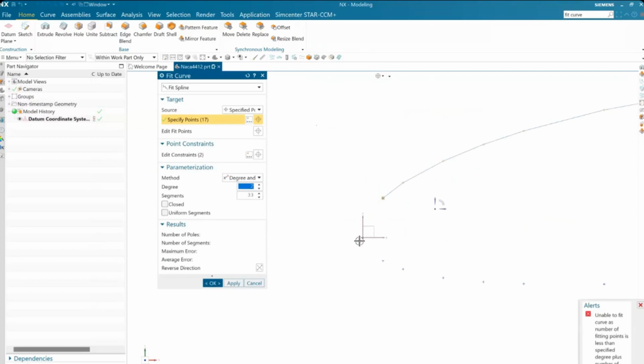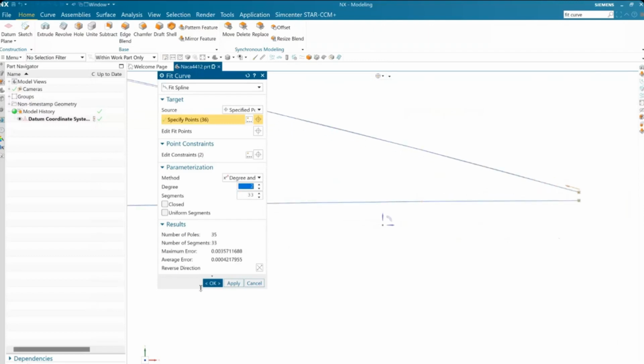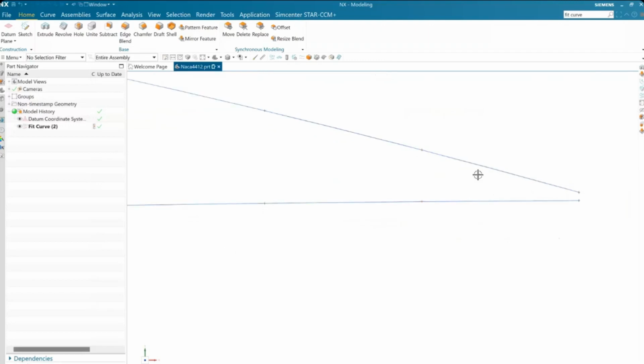Be careful when you get here, because I know that this airfoil includes a point at the origin, so I'm going to select the origin. Some won't, and if you accidentally select the origin, you won't have the correct airfoil, or something bad will happen. But yeah, pretty much just select all of these. Select, that was wrong. Shift, deselect, very easy, and then we'll select this last point. And essentially you want this number as high as possible until it tells you error. Okay. The more data, the higher the amount of segments.